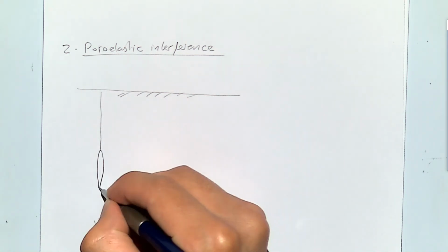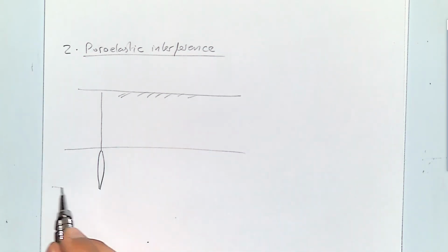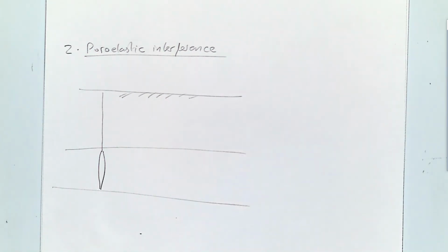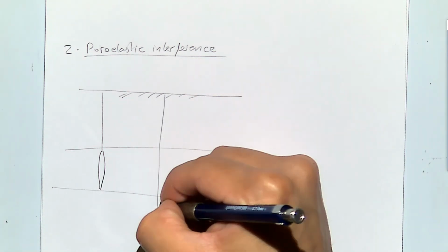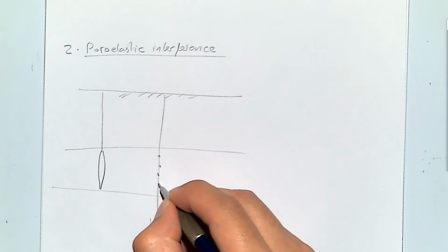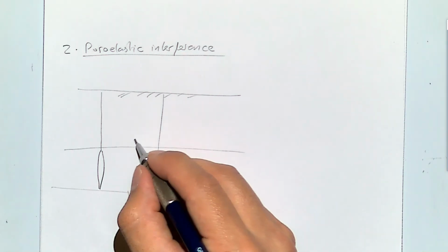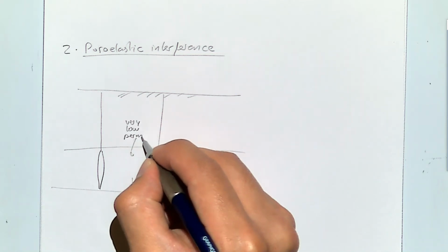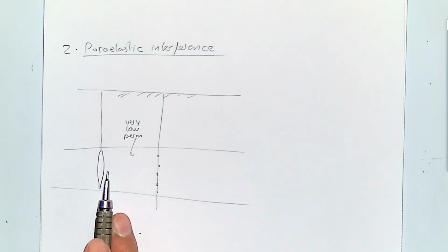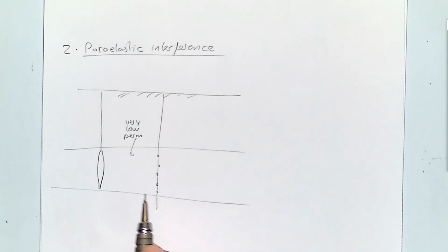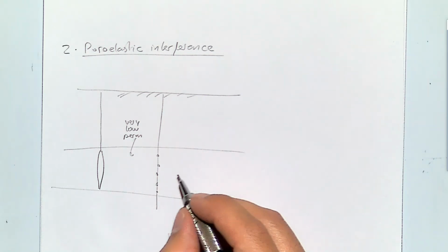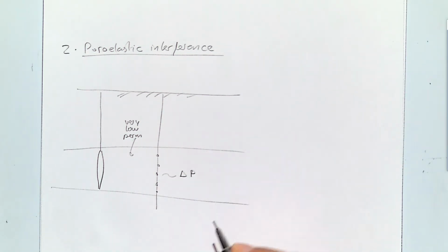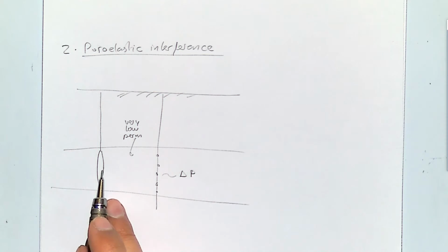Let's make it simple. If you have a monitoring well somewhere over here with pressure sensors, and again, if we're assuming that this is a very low permeability rock, even without having fluid that moves from here to here, just because of the effect of compressing the rock, you may have a change of pressure measured in these sensors, just because you are deforming the solid.